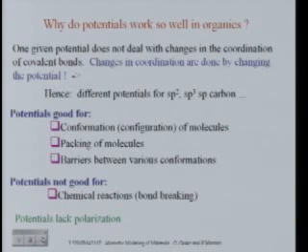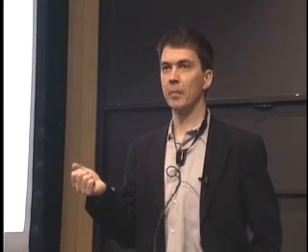Potentials work remarkably well in organic systems. And that seems to be at odds with what I said in the beginning, that pair potentials in particular are bad for covalent materials. But you have to remember why they are bad, because it's the same reason why they're so good in organics. The reason pair potentials are bad in metals is because you cannot capture the energy dependence on coordination. Remember, if your coordination stays the same, if your average density around you stays the same, you're actually doing very well with pair potentials in metals.